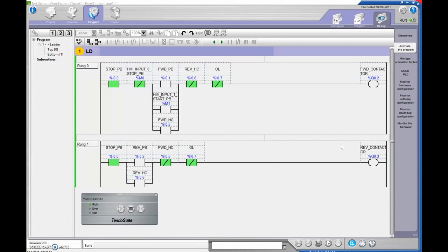Excellent. Okay, so everything's working. I'm able to talk to the PLC. All of my physical push buttons are working. Program seems to be cool. So now we can move into dropping in that HMI signal. It's imperative that you double check each piece at a time as you go. Otherwise, there may be too many things in play that you've changed and you won't be able to figure out what exactly you need to change in order to make it work. I believe that's all of the settings that we need to do so far for the PLC. So now let's move into our HMI program.